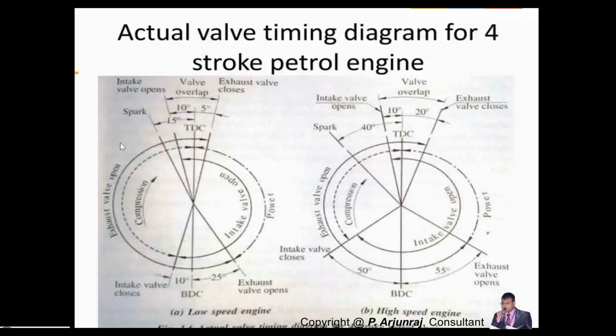But it is not exactly happening at the TDC position, because in the case of actual, it will happen before. Even the valve opening and closing will happen either after or before. It is not going to happen theoretically.